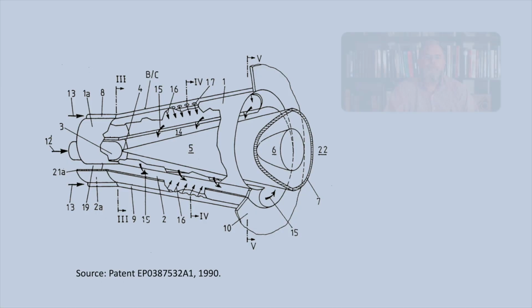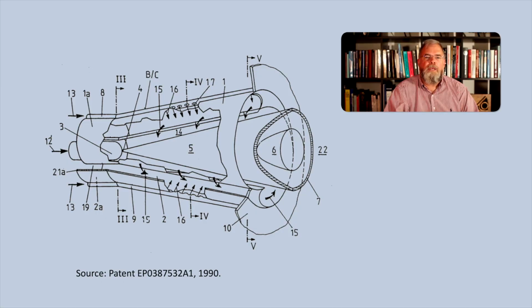Brown-Boveri merged together with ASEA to become ABB, and this company, together with Dr. Jakob Keller, developed one of the simplest and best performing premix burners, which became the main burner design for most of their new engines, known as the EV burner. This burner first saw service in 1993 in a GT11 engine in Midland, USA.